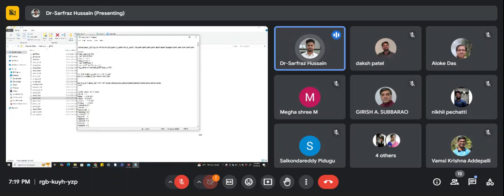If you open this file, you see the definition of the NMOS. So what is this definition? The circuit is called NMOS_3P3. That is the name of the NMOS according to the technology, the name given to the NMOS. So NMOS_3P3, and the connections are in this way. Whenever we are defining that particular NMOS, it is drain, gate, source, and bulk.